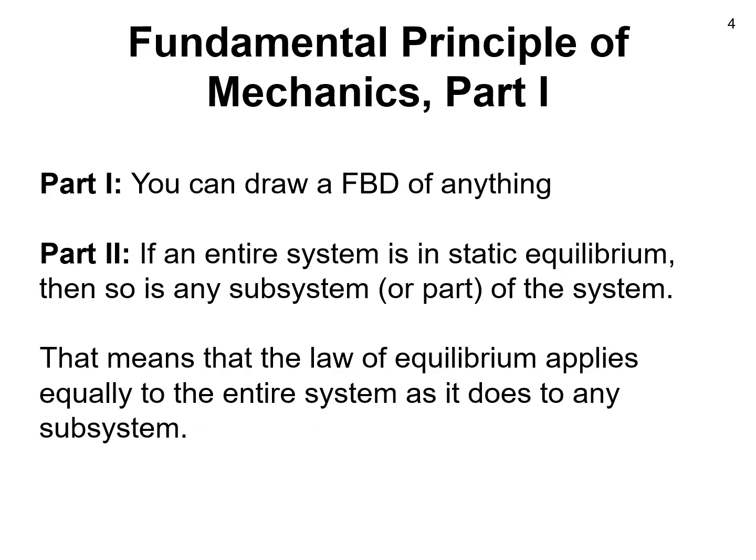Let us also come back to this fundamental principle of mechanics. Part 1, which we discussed in the last module: you can draw a free body diagram of anything. Part 2 then says, if an entire system is in equilibrium, then so is any subsystem or part of that system. That means that the law of equilibrium applies equally to the entire system as it does to any subsystem. So when I say you can draw a free body diagram of anything, that also means that you can then apply the law of equilibrium to that thing that you drew.